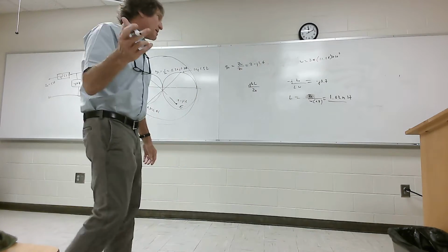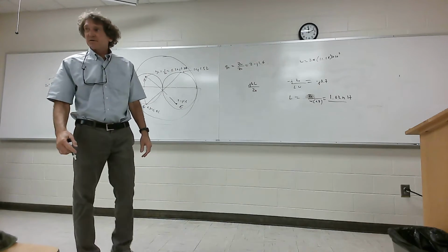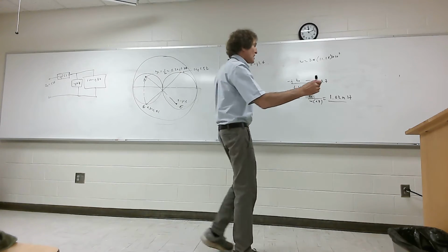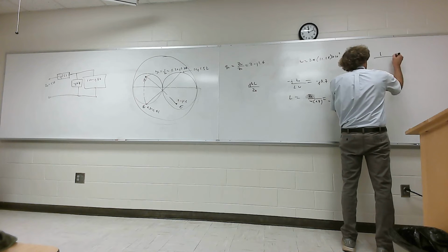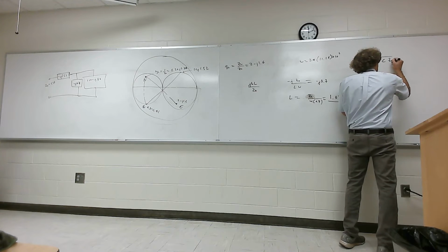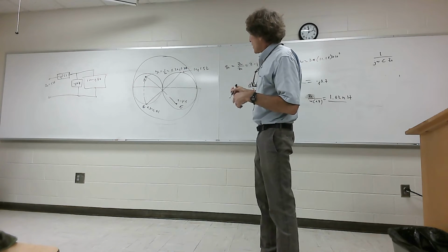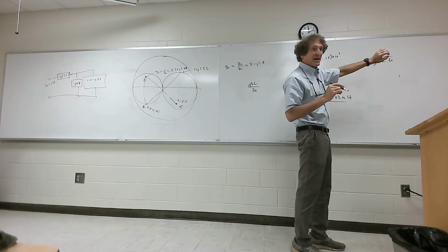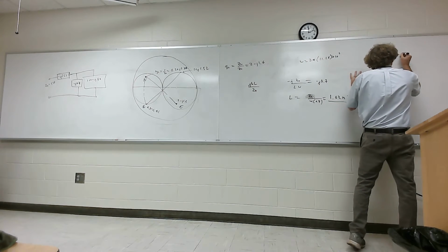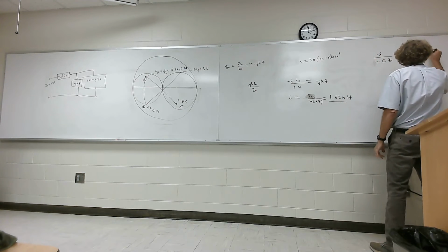How do I get this value right here? That's a series element. It has a normalized impedance of minus J 1.52. It's going to be a capacitor, right? So capacitive reactance is what? I do it this way. I start as 1 over J omega C. Then I normalize it, divide by Z0. Oh, I'm sorry, this is what I need. My bad. That is the normalized reactance. This becomes minus J on top, and that's equal to minus J 1.52, right? You can figure it out from here.